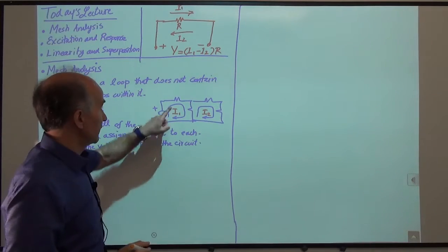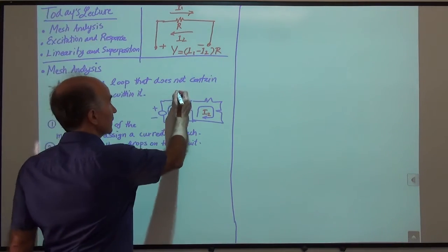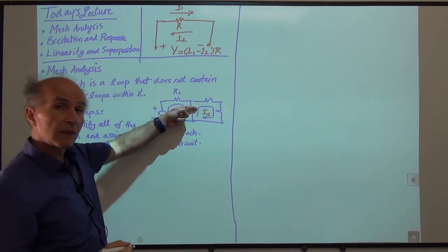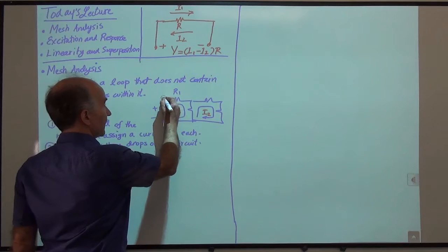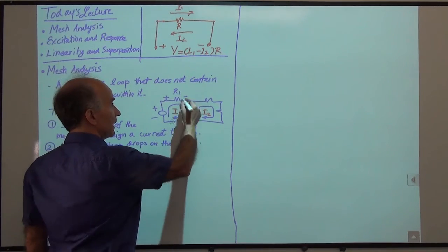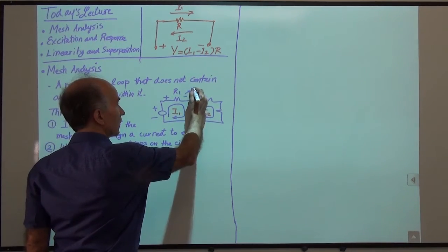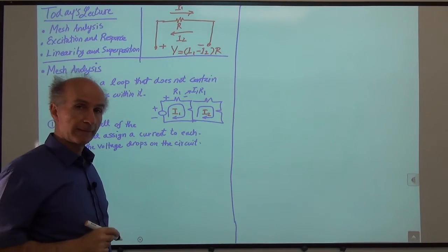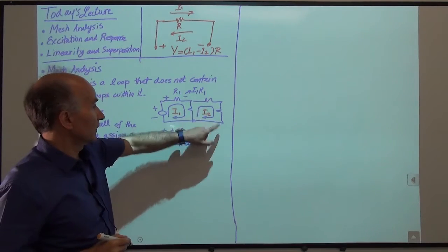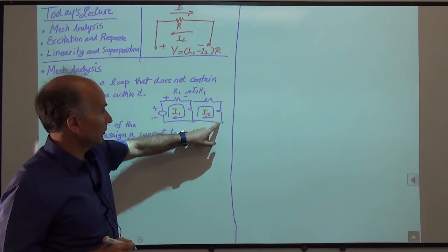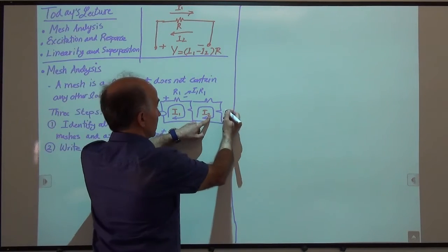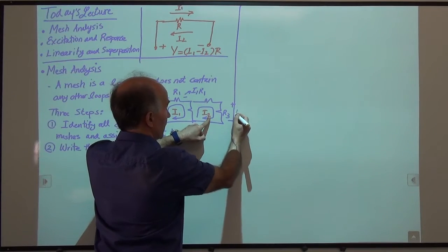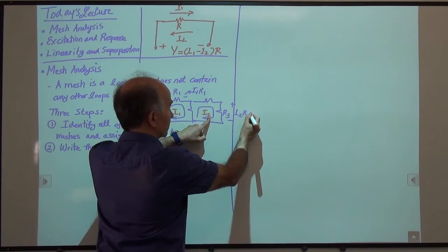For example, if the resistor is called R1 and the current I1 is flowing from left to right, then it generates a voltage across it, and that voltage would be positive here, negative here, and the voltage value will be I1 times R1. Okay. Similarly, this resistor has a current going from top to bottom called I2. So if this resistor is called R3, for example, then the voltage drop from here to here is I2 R3.